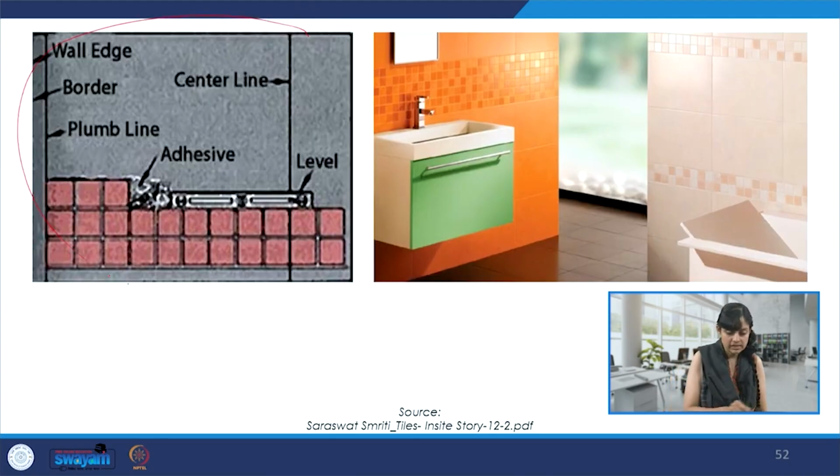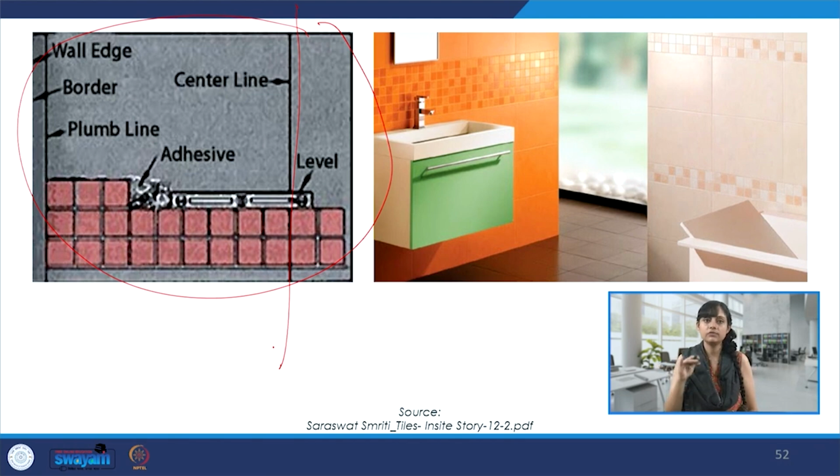Also, again, these kinds of details: what is the center line, what is the level till which the tiling is done, where the adhesive is required, where is the plumb line, so that the tiles are not misaligned, and so on.